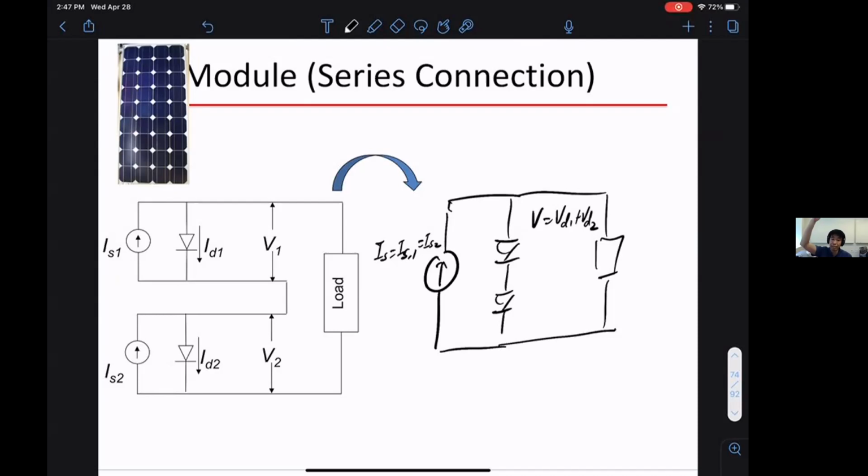So you have 10 in series. One of them gets covered by a cloud, or the sunlight comes from another direction and you're covered by shadow. Then you lose current in this entire series branch. So that's a loss of efficiency. This is a very practical problem we actually have. Often partial shading is really a problem on your roofs.